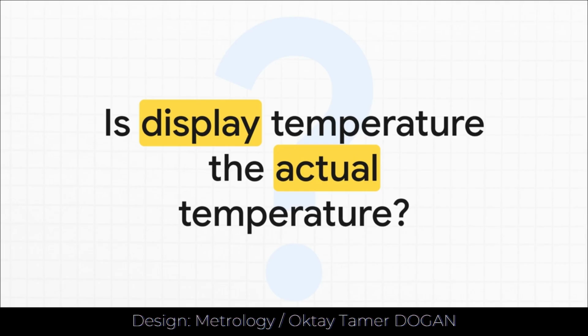No way. The reality is that a climatic chamber is a churning, dynamic weather system. You've got varying air velocities, thermal radiation bouncing off the walls, drafts, and subtle hot and cold spots. That display, it's really just one single sensor's opinion. The DKD R 5-7 guidelines exist specifically to map out and quantify the chaotic reality happening behind that closed door.